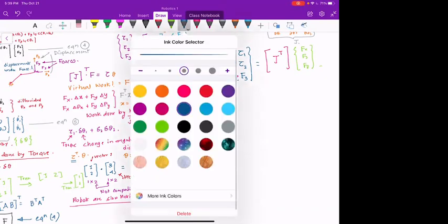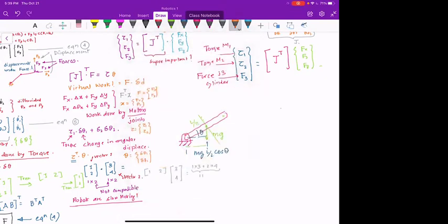This torque is going to get applied if the robot is at its position shown. So the idea is, the motor that you have over here is supplying the torque, tau, that is compensating the torque or the moment given by gravity, so that this robot arm stays in this equilibrium position. So that is what the motors are supposed to do. So there is something called the static or the holding torque. So tau, think about it as holding torque.